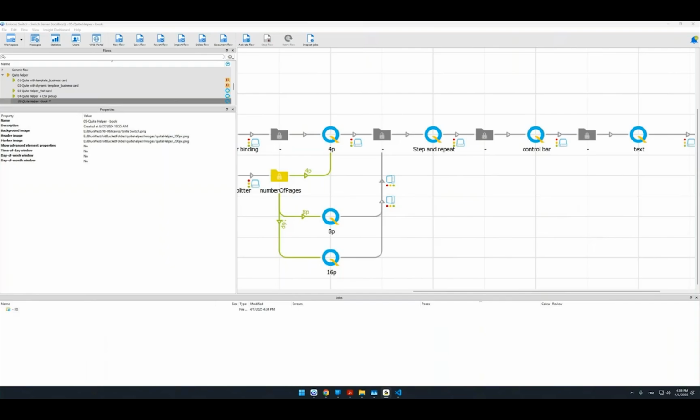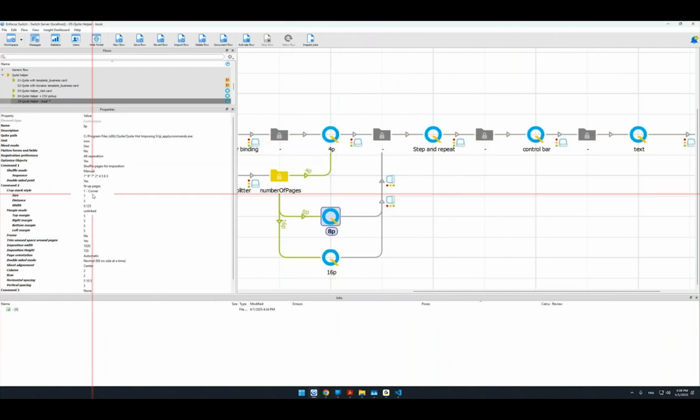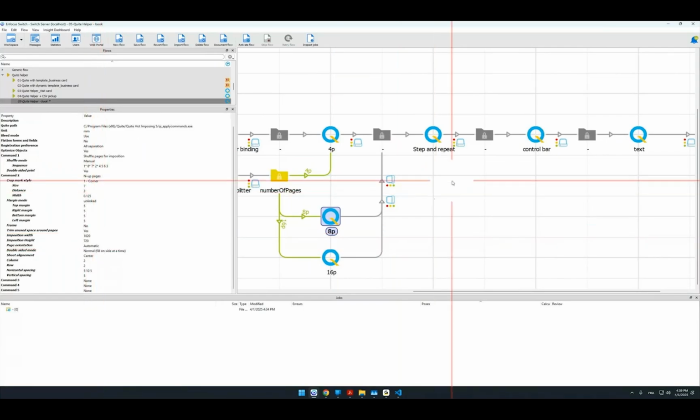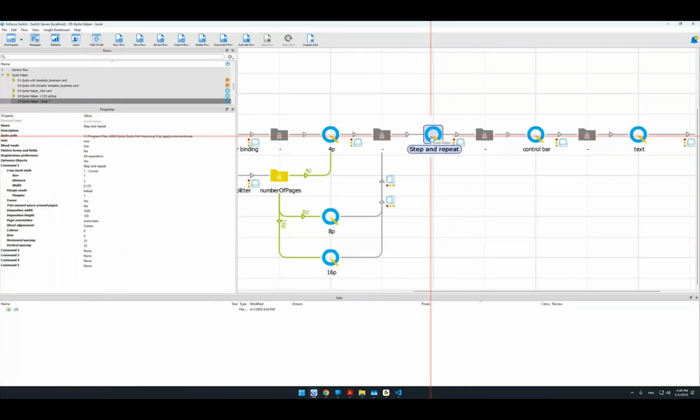Another question from Magnus: is there a roll media option where you can choose the roll width and maximum length? Vigo already responded no, but you can use trim unused space around pages and then define final size with fixed width and variable height. Yeah, that's the way. You could create it in two steps. Just use the trim option, and then create a step and repeat one by one. But when you need to create a sheet size, just grab the size you want to be fixed, and let the second one be the same as the first.